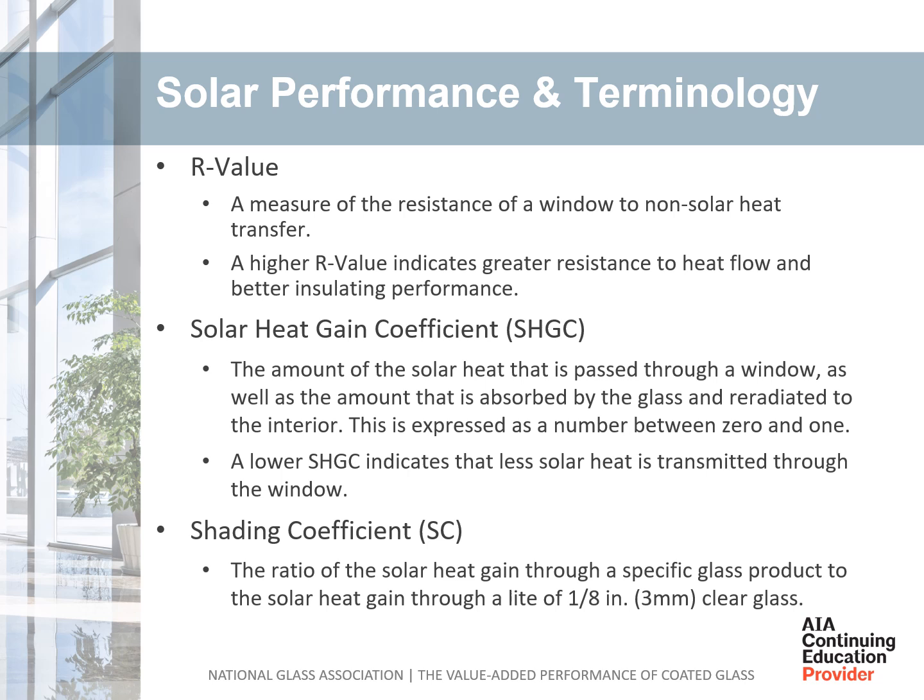Finally, shading coefficient is a measure of the heat gain through glass from solar radiation. Specifically, the shading coefficient is the ratio between the solar heat gain for a particular type of glass and that of 1/8 inch thick clear glass. In effect, the lower the number, the better the performance. 1/8 inch clear glass would have a shading coefficient of approximately 1.